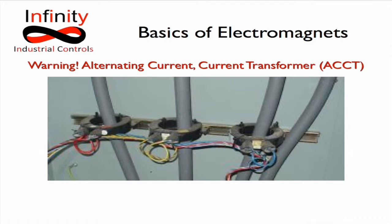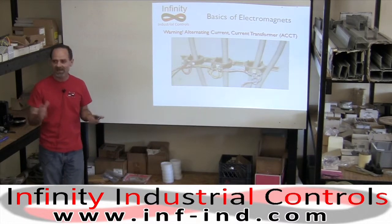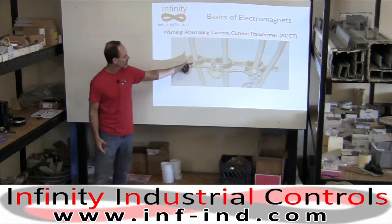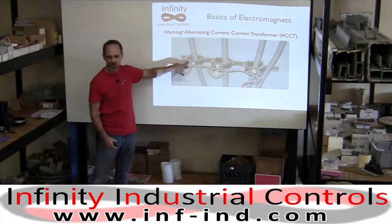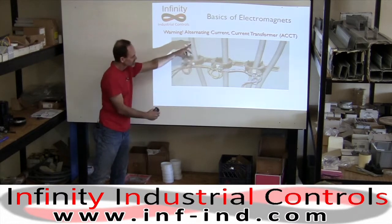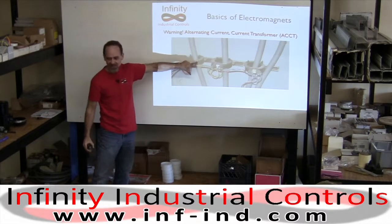Have any of you ever seen these current transformers? These are basically coils like we looked at before. If you pass a current through a coil, it'll produce a magnetic field. Conversely, if you pass a magnetic field over a coil, it'll create a voltage. Okay? And that's what these are. These are coils, and these are power lines. And they put these around those so they can pick up current, and these are called current transformers. They pick up the magnetic field. These being alternating, that magnetic field alternates backwards and forward, alternately plus and minus. So this picks that up, and you monitor it.